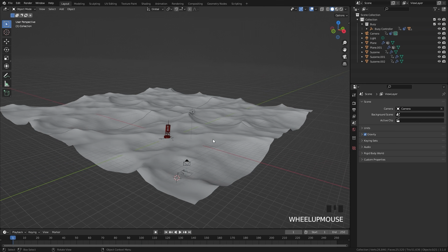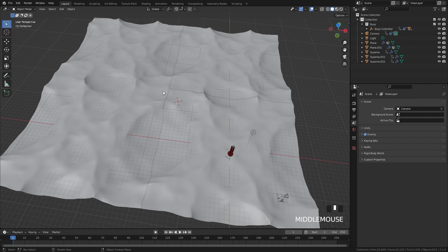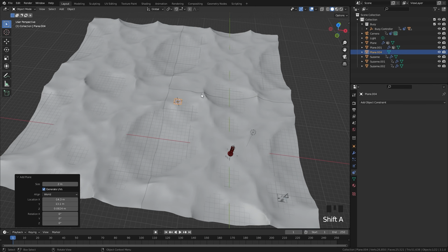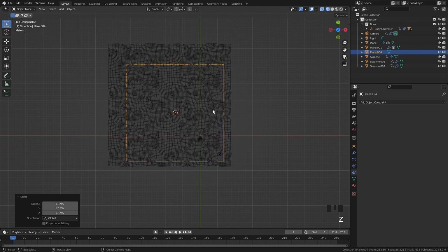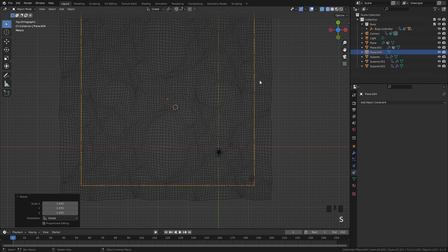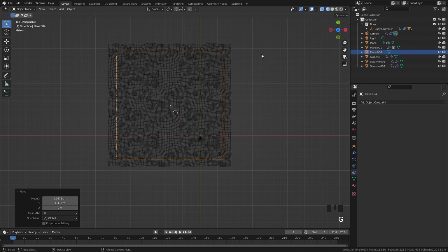The next thing that we'll do is create the ocean that's underneath. This is going to be a very large cube with a volume material. So what we need to do is first place our cursor right in the center of the ocean. Then we're going to add in a plane object. We're going to go into top view and scale this plane up so it fits the ocean. Something like this, but you don't want to go past the edges, so right about there looks pretty good.